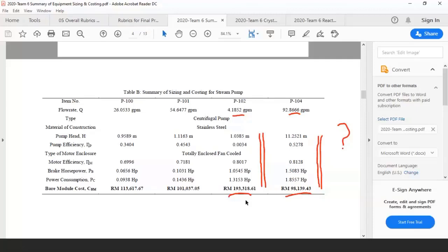Okay. Noted. Actually, in reality, when you want to purchase a pump, now this is your level at the moment, you refer to the textbook. But in reality, when you are working as an engineer, you will actually refer to the pump curve fitting, where there will be the head loss, the flow rate, the kilowatt or horsepower, the impeller size, diameter dan sebagainya lah. Okay, there are many things.